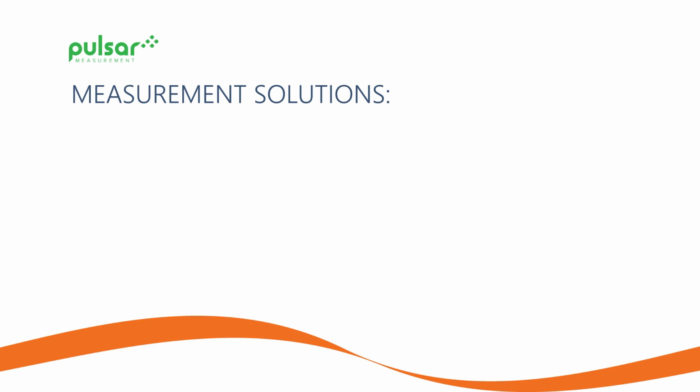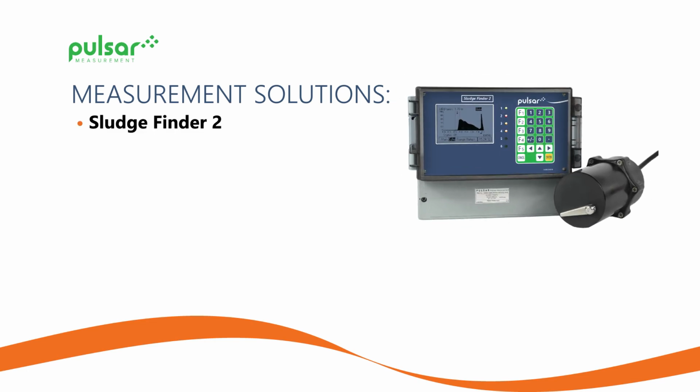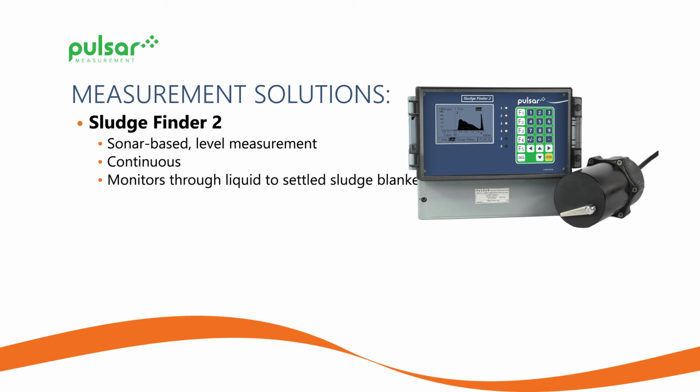In stage 6 of the process on the clean water cycle, Pulsar recommends its measurement solution, the Sludge Finder 2. The Sludge Finder 2 is a sonar-based level measurement system, but continuous. It's not a point measurement. It monitors through the liquid down to the settled sludge blanket. From here, we can avoid passing on unnecessary solids into the filtration stage itself, further blocking that process and also increasing costs and more backwash cycles on the filter. So Sludge Finder 2, straight into the settlement process itself, can offer you automatic desludging, reduce man hours and process time on site.